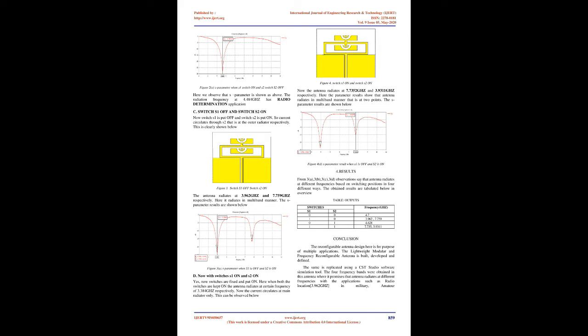3. Proposed methodology. The whole process of designing is done in CST MWS. Here the antenna designing is done first, on which the switches are altered accordingly. Switches S1 and S2 off. Here coming to the process of designing. Now the two switches are involved in current transfer. The two switches S1 and S2 play a major role here. These switches are placed at inner and outer radiator respectively.